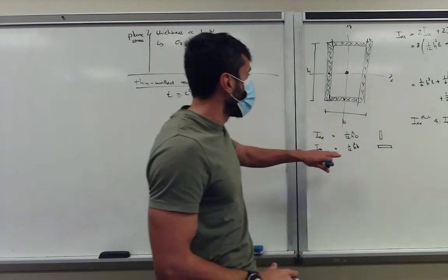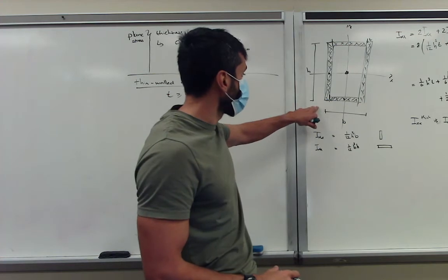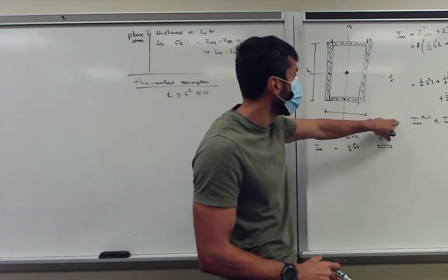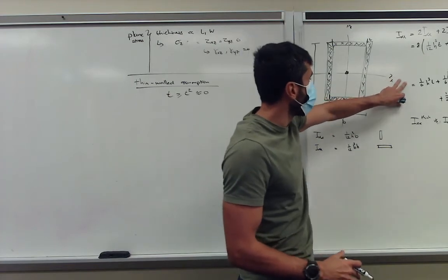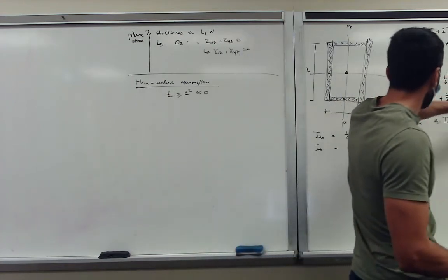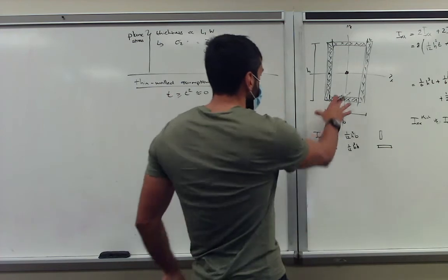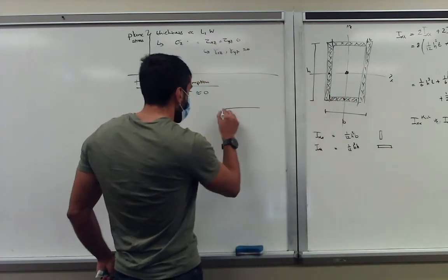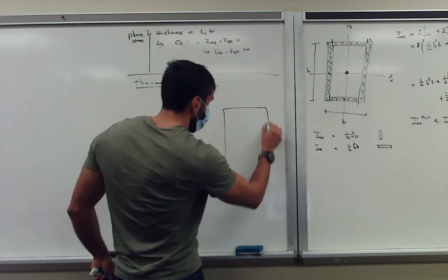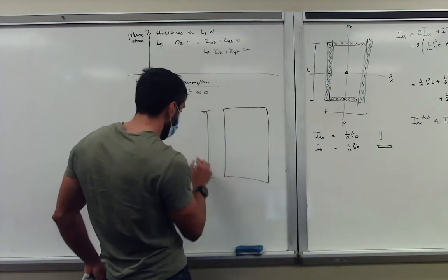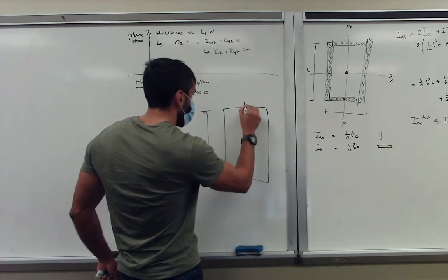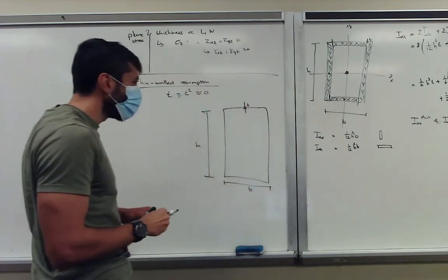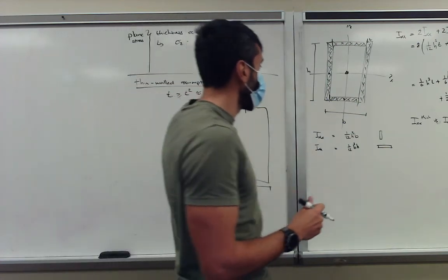So, why does that make sense? Well, this is the reason why it makes sense if we do both. In order to avoid this complicated equation, what we basically say is this structure is no longer thick walled. We say it's thin walled. So now we basically say this is equivalent to this structure where we have h, we have thickness everywhere, and we have b here.